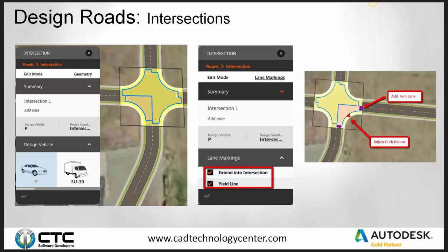And then finally, if you click on one of the curb returns, so you highlight one of the segments, I can actually manually adjust the curb return. So maybe it's a standard passenger car for this intersection, but this northbound lane will be leaving a supermarket, and it knows that you're going to have semis that will be making a right-hand turn here very frequently. The semis will be coming in from another intersection to get to that supermarket. So they know that they only need to adjust this one curb return and not all four for a semi truck.